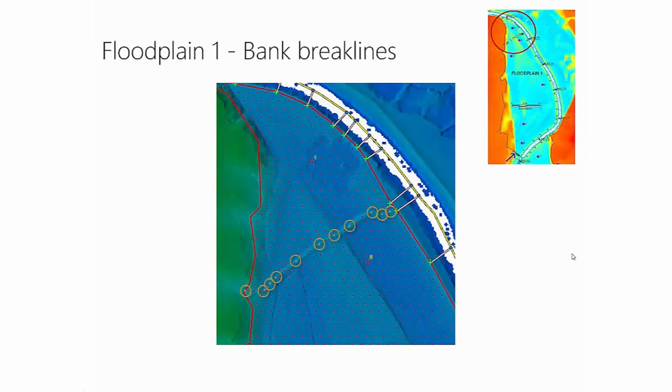Now one of the challenges we faced with this model was this berm and how to represent it. What happened was the resolution of the mesh was too coarse and links were being drawn that bypassed the berm. So what we had to do was go into the model and add additional 2D nodes to that section. Alternately, you could use a break line layer. It's basically a line layer that you draw, and PCSWMM would ensure that it would draw the 2D nodes along that line.